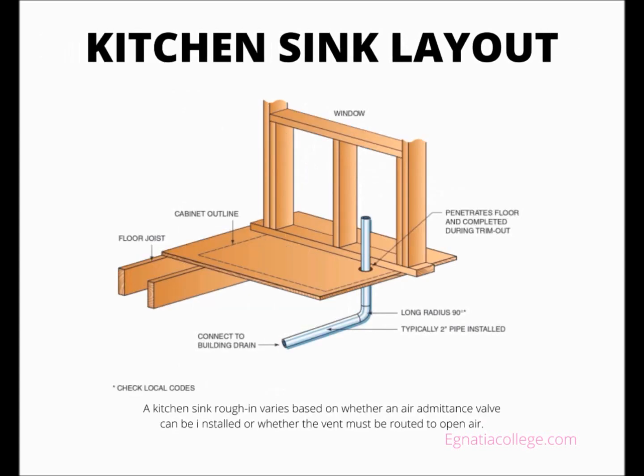Kitchen sink layout. The kitchen sink is centered directly below a window, and the exterior wall studs are load-bearing. If your local code allows an AAV, it can be installed below the kitchen sink to minimize labor costs.